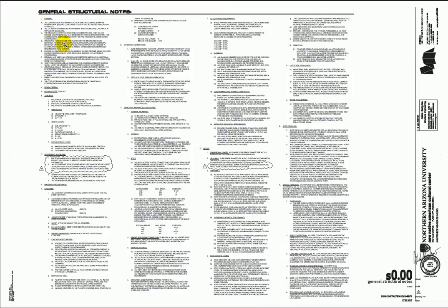So I'm going to go back to the beginning, the general structural notes, and the general structural notes really give the detail about this type of building. There are specifications that will tell exactly how to build each part. However, the structural notes are different than most other trades where the specs take precedence. In structural drawings, typically it's the structural notes that take precedence over the specification. So let's jump in here, and by reading through the general notes, by skimming through them, we can get a good feel for a lot of the assumptions of this building and the materials.